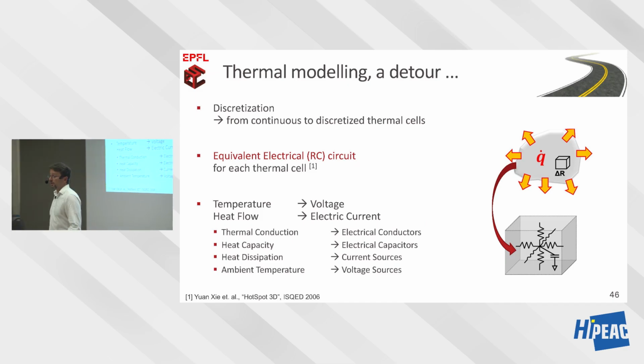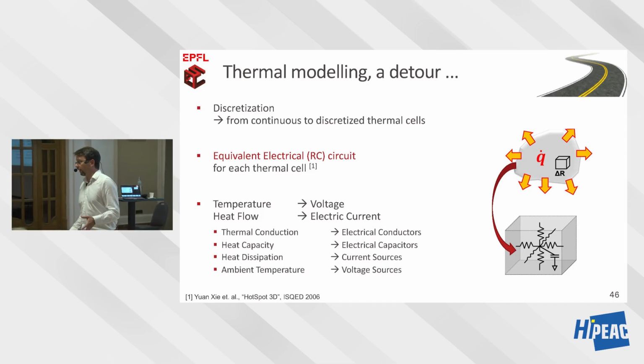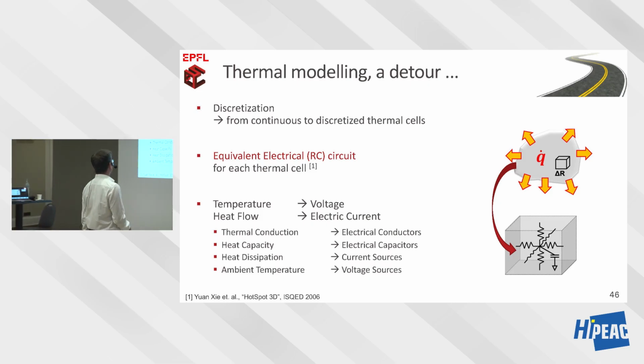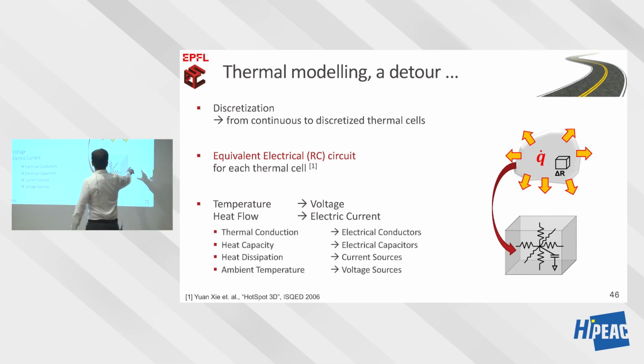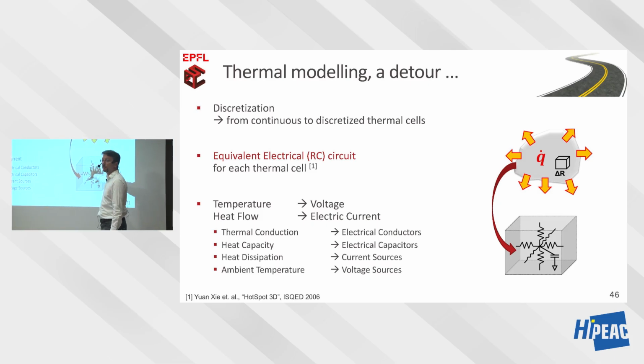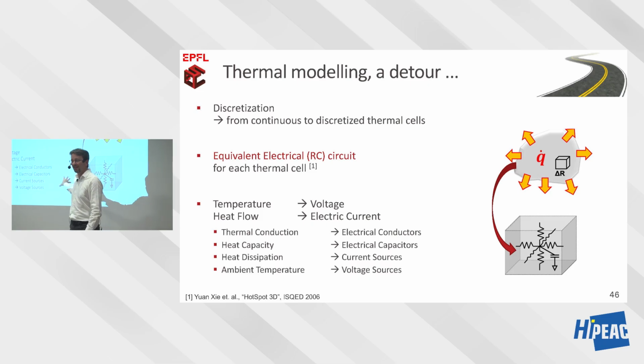Here starts a big aside about thermal simulation. This is based on the equivalence between thermal and electric characteristics. If you have a good electrical simulator, such as a quantized finite element simulator, then you can also make a good thermal simulator out of that. You just say that the temperature is equivalent to the voltage and the heat flow is equivalent to the electric current. And you can do exactly like equivalent electrical circuits, which model the heat instead of modeling electrical characteristics.